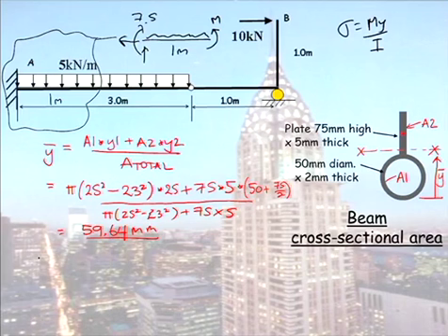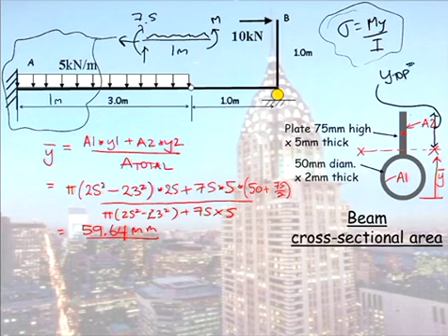So now, when we come and use our formula here, what is Y? Y is the distance from the neutral axis to the extreme fibres. Because remember, my bending stress distribution is triangular. So that distance in here, I'll call Y top, and that's equal to 65. And that distance in there is Y bottom, which is equal to my 59.